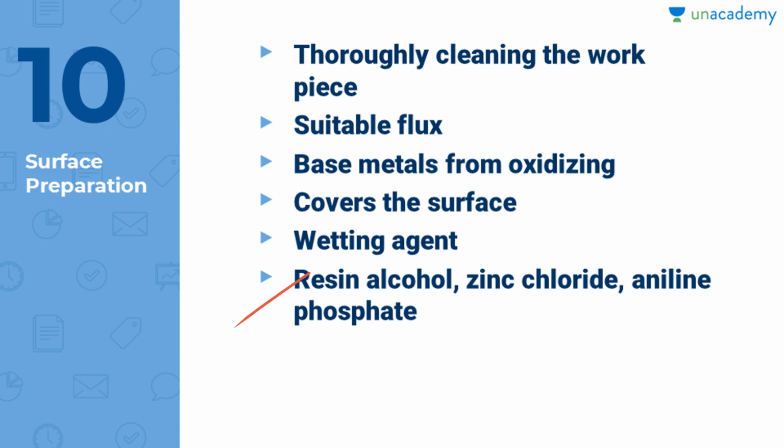Different types of flux can be used, which include resin, alcohol, zinc chloride, aniline phosphate and so on. The flux may be applied to the metal surface by brushing, dipping, spraying or by other methods.